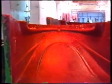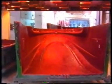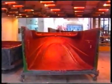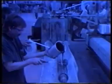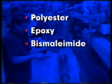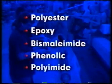Thermosets require curing to develop their full mechanical properties. Once cured or set, thermosets cannot be reprocessed. Some of the primary thermoset matrix materials are polyester, epoxy, bismaleimide, phenolic, and polyimide.